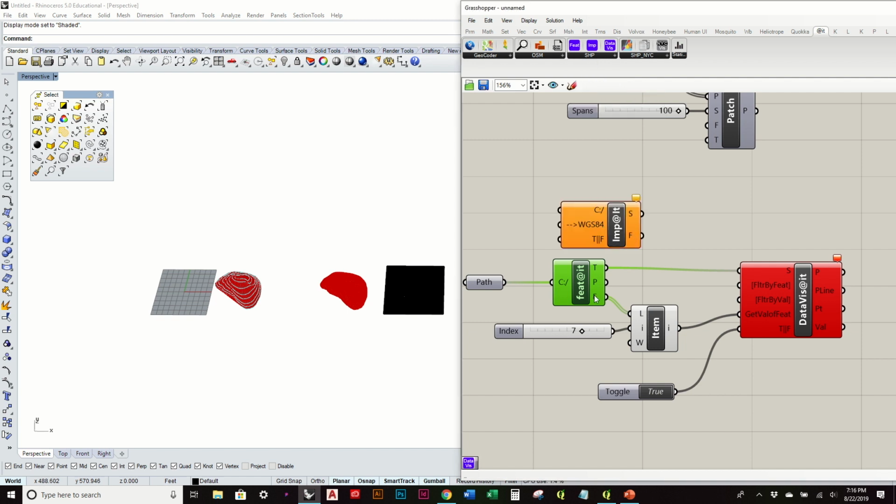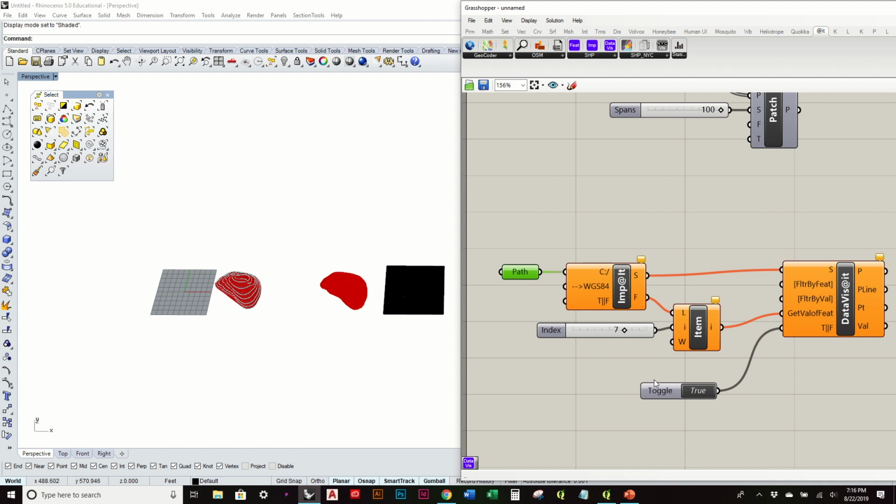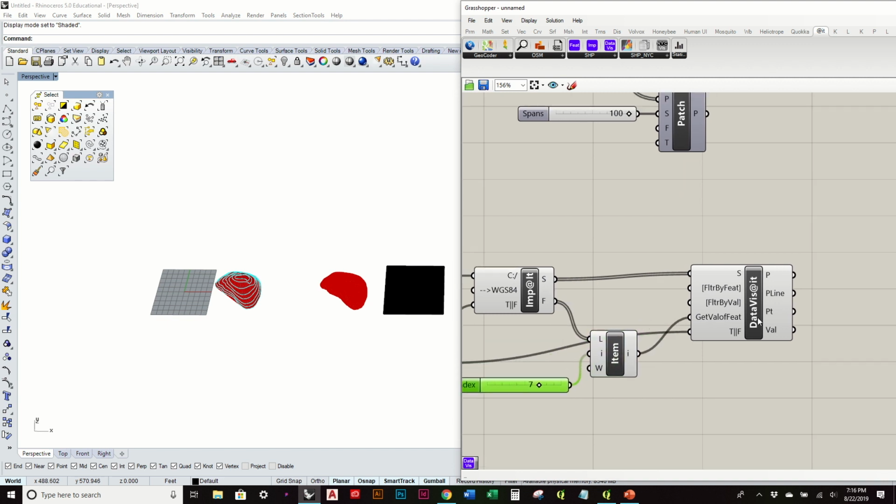Let's do the import one actually. So that's usually a good rule of thumb. I don't know why. It's the T into the S. That's usually the issue. But let's go ahead and plug this. Everything else should stay the same. This F is going to the list item. And this also needs the true and false. I knew that was missing. I should have known from the start that that was the wrong component.